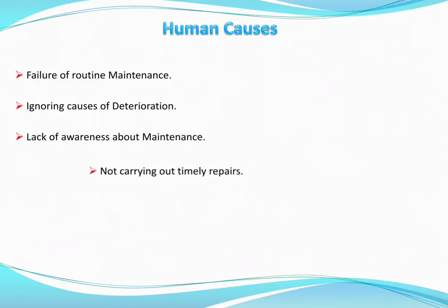Further, we don't carry out timely repairs. If a small crack develops, we don't repair it then and there. We want the crack to become bigger and bigger, and when it starts causing deterioration or problems, then we start hunting for solutions. So not carrying out timely repairs is also a very important factor.